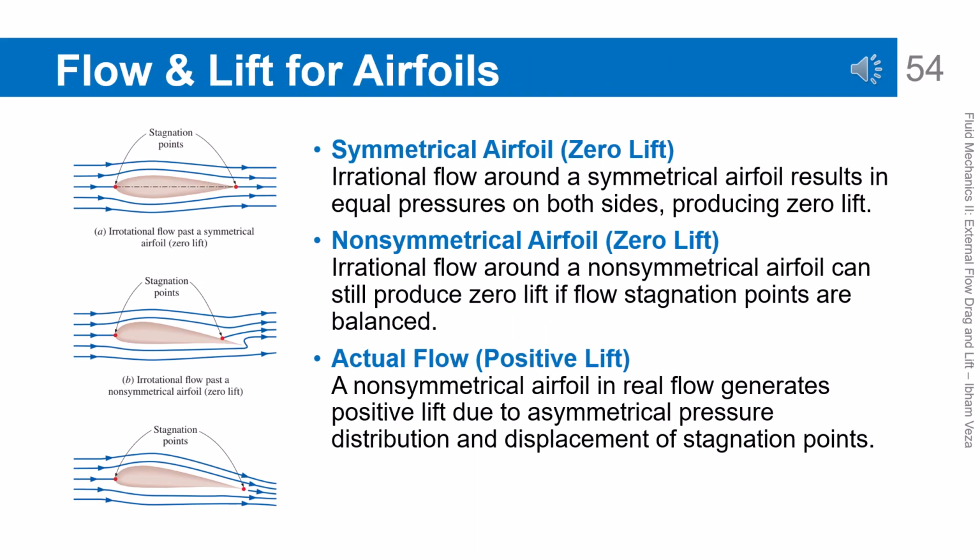Flow and lift characteristics for airfoils. In ideal flow, a symmetrical airfoil produces no lift at zero angle of attack because the pressures on both sides are balanced. A non-symmetrical airfoil can also produce zero lift if the stagnation points are balanced.